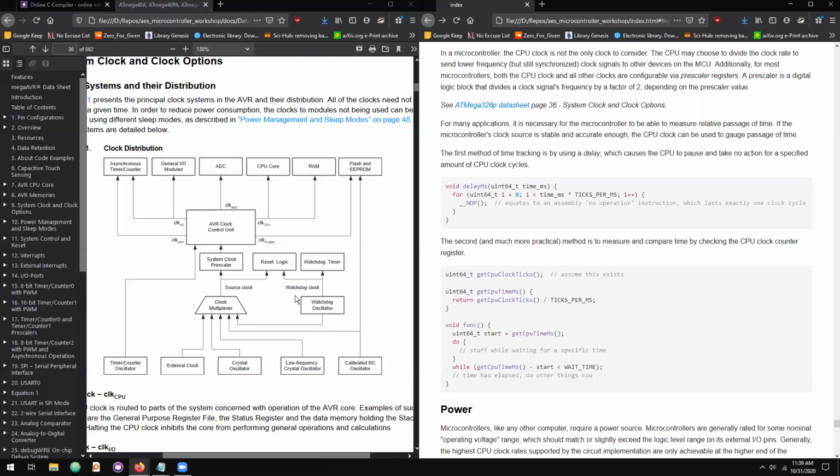And so how many clock cycles are there per millisecond? And now finally we have a function that's equivalent to the Arduino millis call. So it tells you how many milliseconds have occurred since the microcontroller got power. And so we can use the difference in calls to actually determine the difference in milliseconds that's occurred.